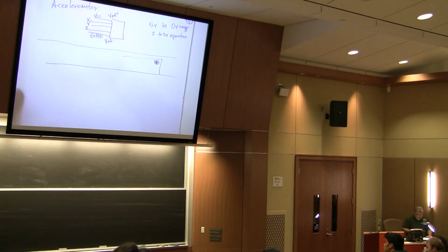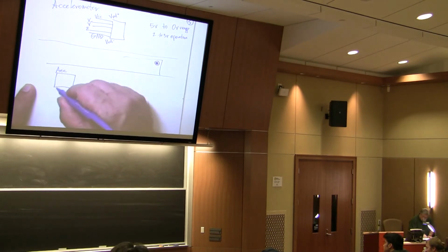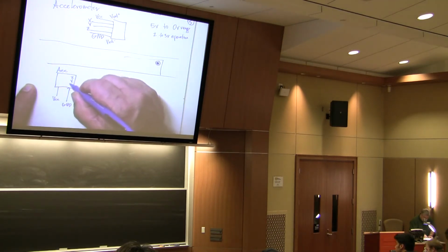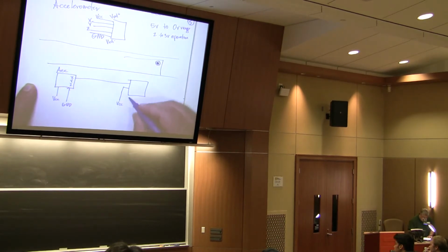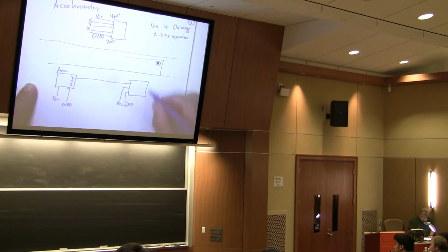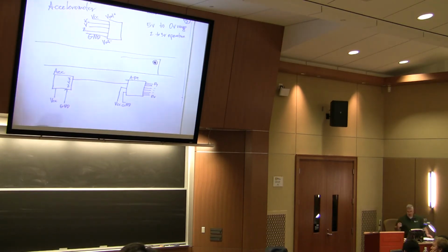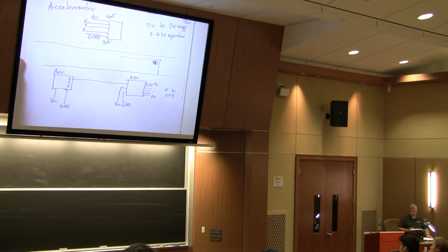So if you have an accelerometer as an example, how it would be in your circuit is your accelerometer would have supply voltage VCC and ground. Remember I said X, Y, Z, but that would go to another chip, which would typically be connected to VCC and ground. And then it would have, let's say, an 8-bit ADC. You would have your lower data bits all the way up to your upper data bit. And if this were an example of an 8-bit ADC, obviously the accelerometer's values would be somewhere between 0 and 255, so a total of 256 different values.